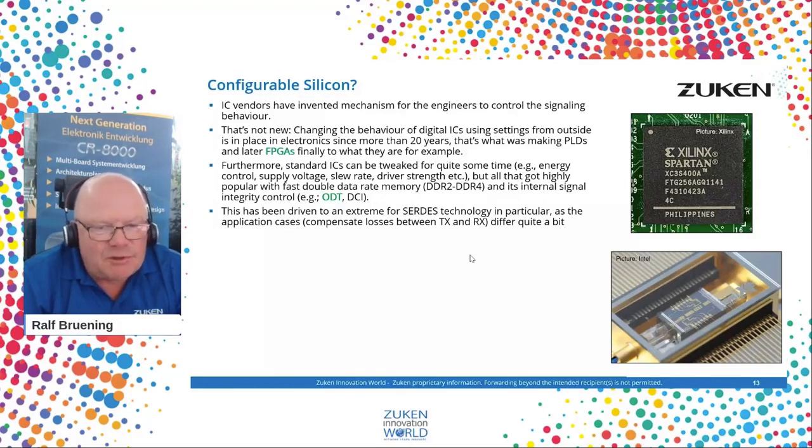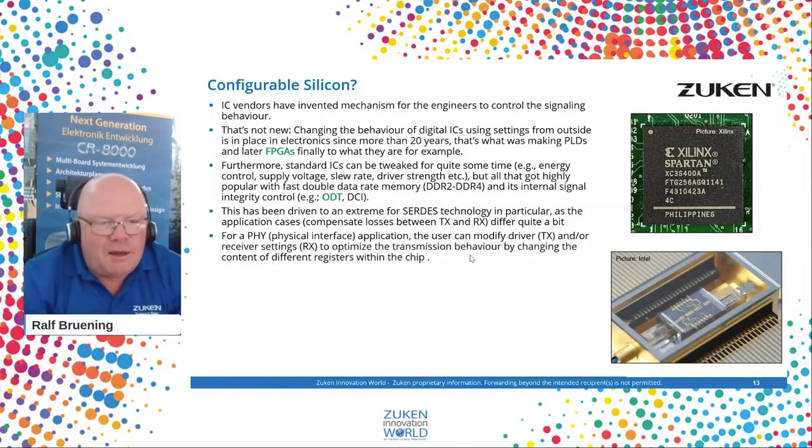That's a mechanism to tweak the signal behavior on the driver side to compensate losses. And you have filtering techniques called equalization, and different equalization schemes from IC vendor A to IC vendor B on the RX side. So that's making SerDes that powerful, but also a little bit complicated.